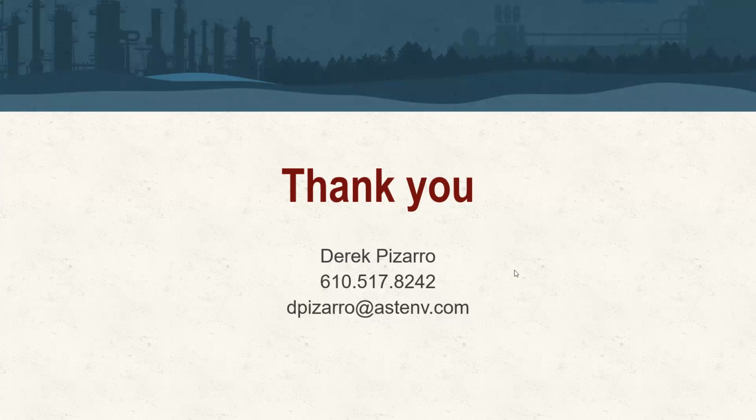Okay, thank you. We got a couple more here. Do you try to determine the minimum demand, similar to soil oxidant demand for ISCO, to confirm whatever is present in soil and groundwater that can be reduced and therefore is a demand on the reagent besides the target contaminants? Or do you simply use your 2% rule of thumb?